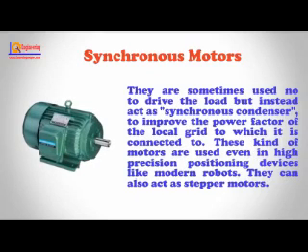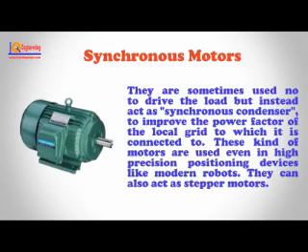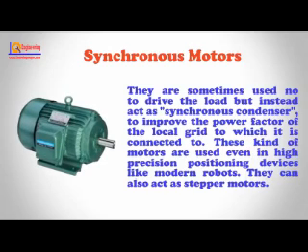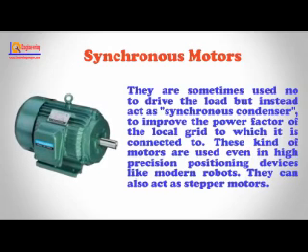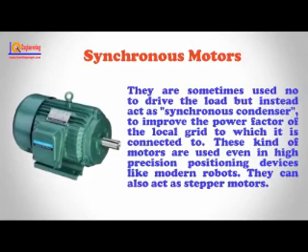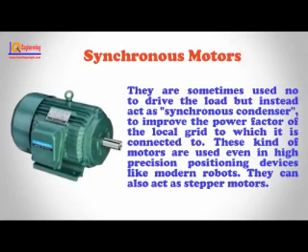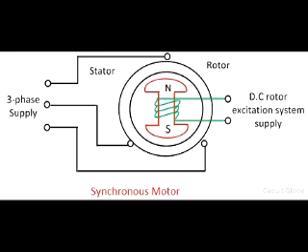The working principle of a synchronous motor: when the supply is given to the synchronous motor, a revolving field is set up. This field tries to drag the rotor with it, but cannot do so because of rotor inertia. Hence, no starting torque is produced. Thus, inherently, a synchronous motor is not self-starting.